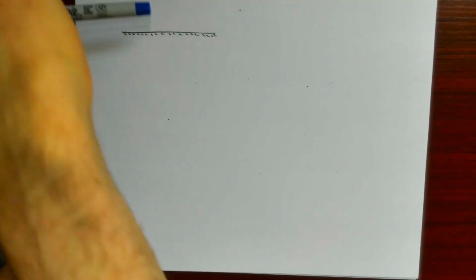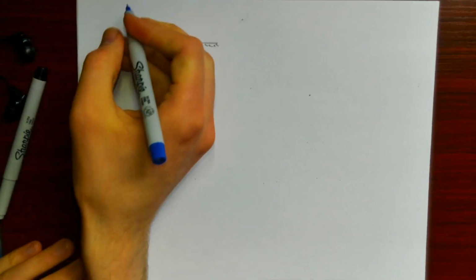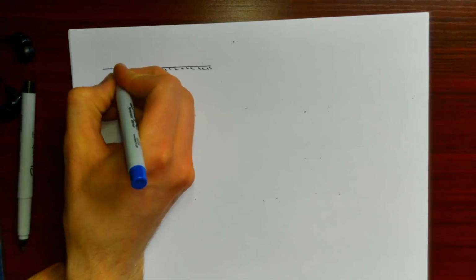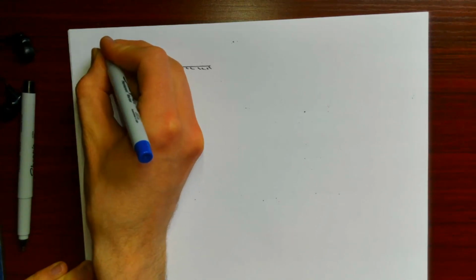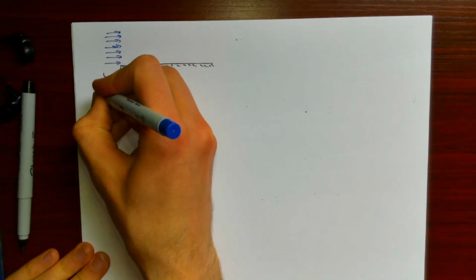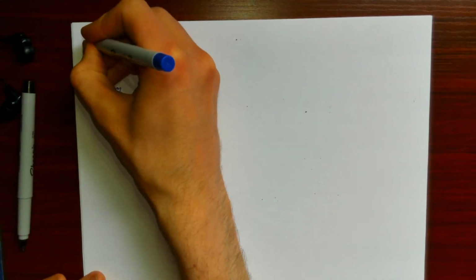And here we're going to imagine a scenario where I have fluid flowing tangentially past that surface. So let's say I have some fluid coming in, there's a leading edge of this plate right here. I have fluid coming in, and before the fluid really encounters the plate, that flow is, give or take a little bit, roughly uniform. So right here we might have this uniform flow, and we might say this uniform flow has some velocity, v infinity.